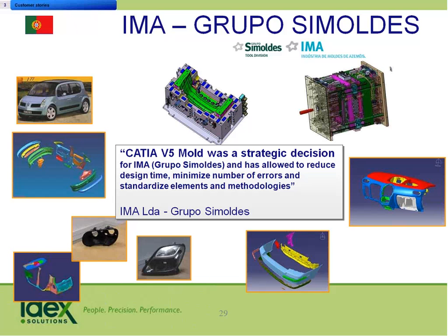I can then actually build my part under load conditions and then take it backwards. So it kind of does a reverse for it. It'll reverse it and take all the information from that part. What it does is it uses an XML file of where all the points were on that part and maps it back. So then it comes in and will take the part and morph the part. It'll go find a surface point on that part and move it to the right position where it's supposed to be. Then we'll actually run another FEA analysis on it typically to make sure that it bends the right way.